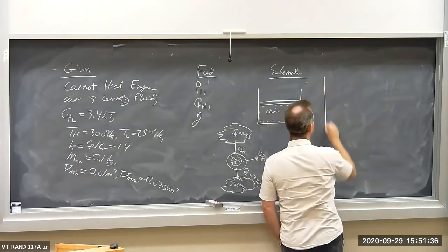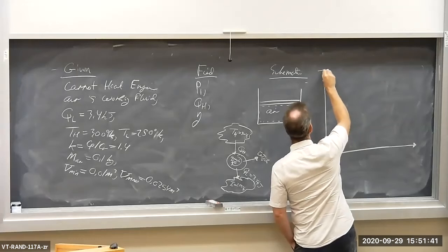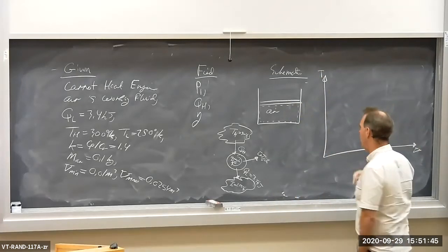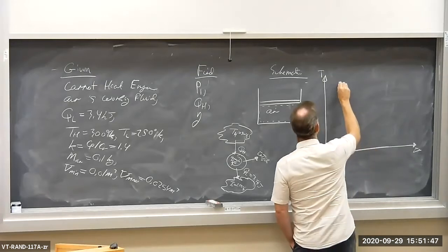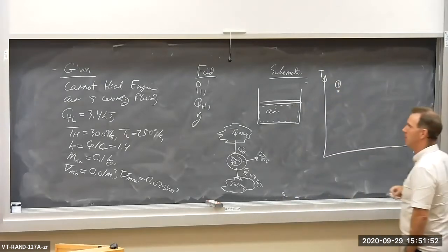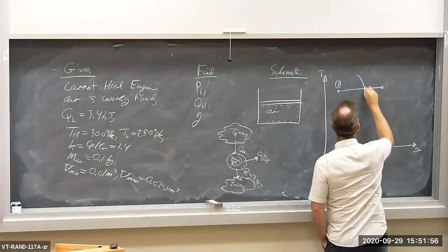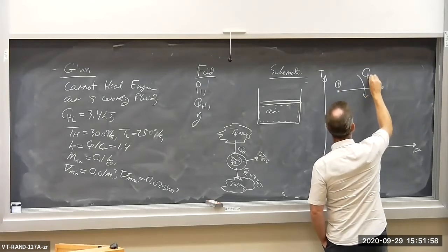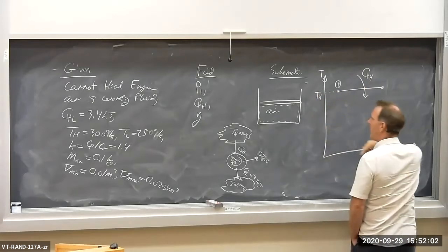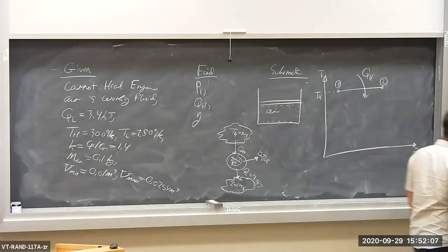You should always put up a TV diagram when you do these kinds of cycle problems. So state 1 is the minimum volume, maximum temperature. 1 to 2, as you recall, for the Carnot cycle is isothermal heat addition from the high temperature reservoir. So the temperature here is T high, the air is at high temperature as we go from state 1 to state 2.